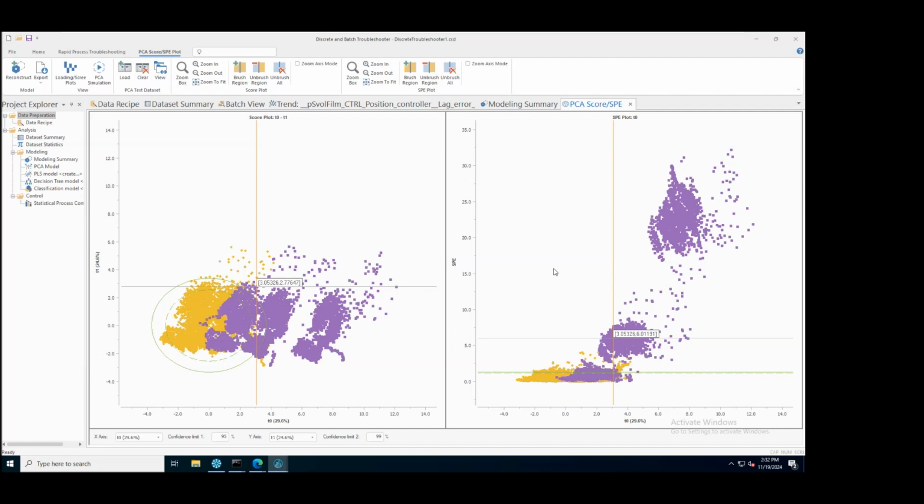So one simple way of interpreting this is you'll notice that we have these dashed green and solid green lines, which indicate to us where 95% and 99% confidence intervals are for our new blade data set. So if we take this and say that we know that 99% of our original data fitted below this threshold, anything above this is truly abnormal operation. And we could use this inside our deployment system to flag this.